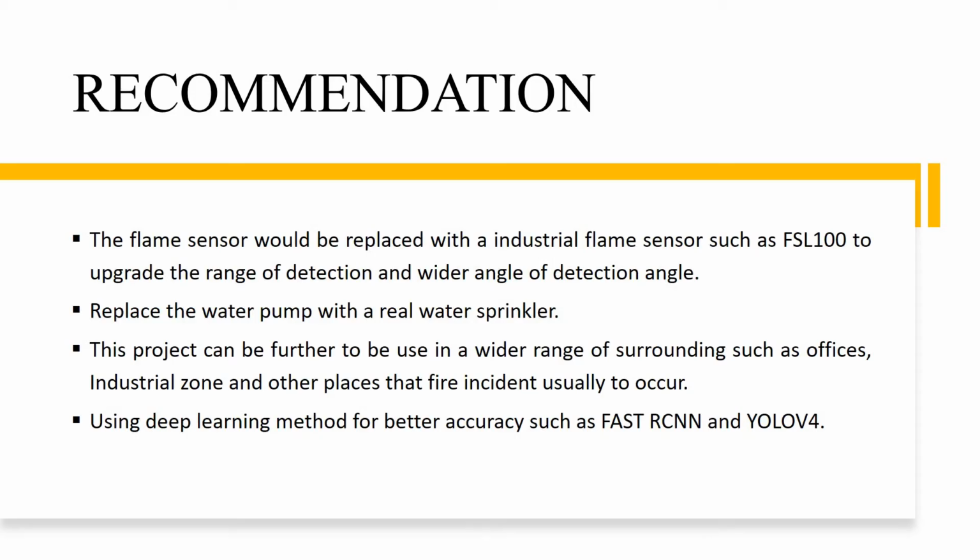So this is my recommendation for this project to be upgraded or to be used in the industrial zone. So the flame sensor will be replaced with an industrial flame sensor such as FSL 100 to upgrade the range of detection and wider detection angle. So the FSL 100 has quite good range of detection and the wider angle of detection.